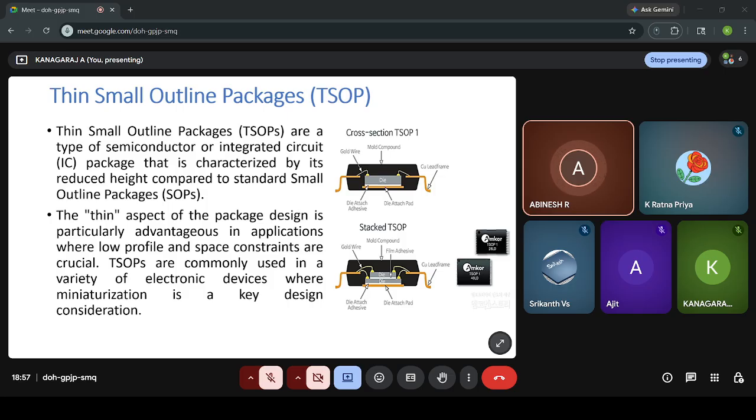Not only SMD or through hole, there are a lot of things. I also mentioned that SOP means small outline package, QFP is a quad flat pin, QFN is a quad flat no lead. No lead means no pin is visible to us, it is built into the chip. Some data sheets should be referred to, but in tomorrow's classes we want to see how to create them.